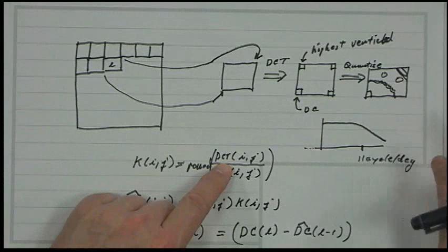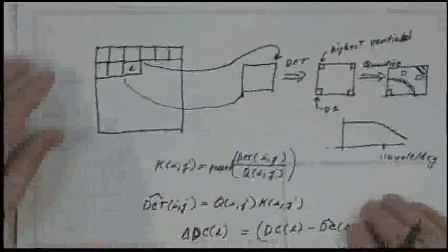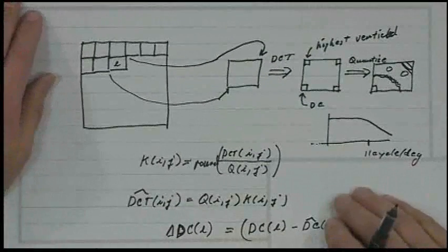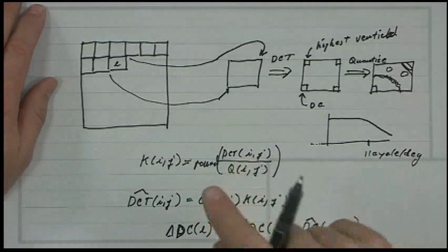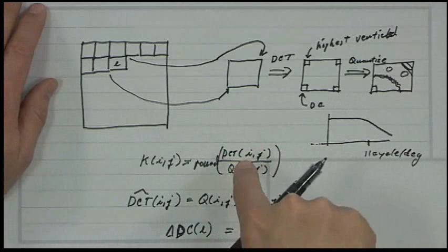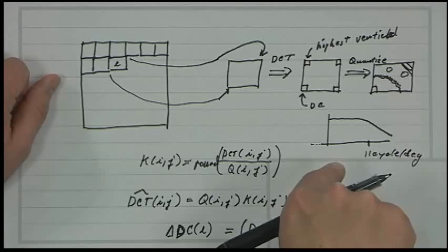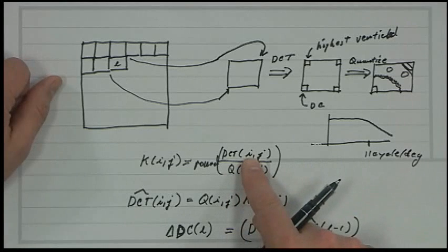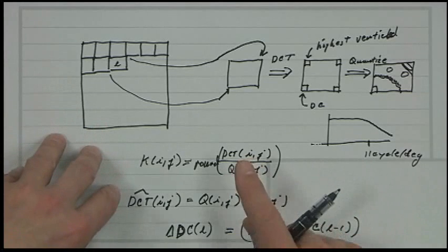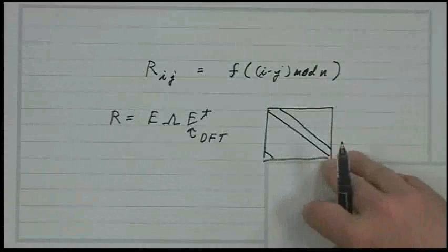Well, the FFT produces complex coefficients, but there's another problem with the FFT. Remember the FFT produces complex coefficients, but they're conjugate symmetric for a real valued signal. So I could just take half of them, and I could figure out the other half by just reflecting them. But there's a more basic problem with the DFT that occurs when the block size is small, and it's a very important problem, so it's a first order effect, which is this.